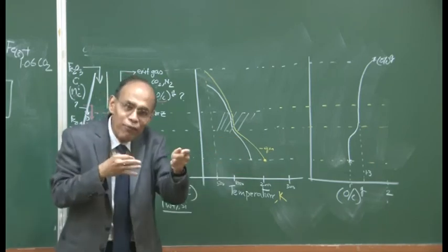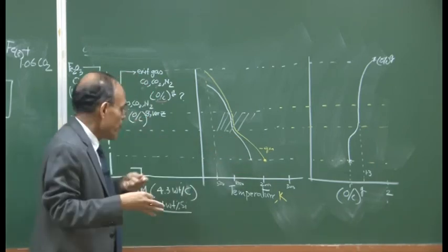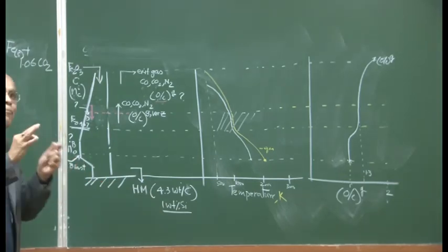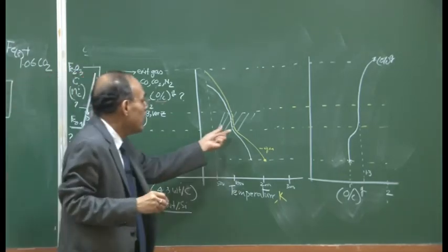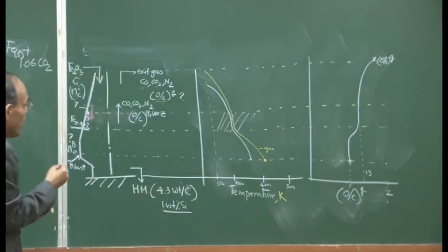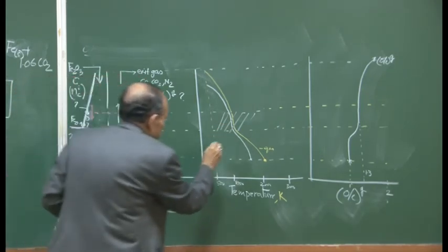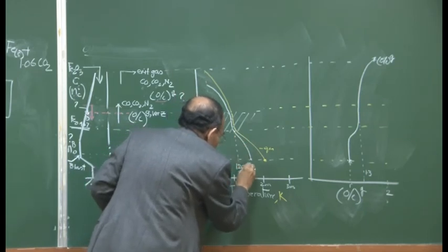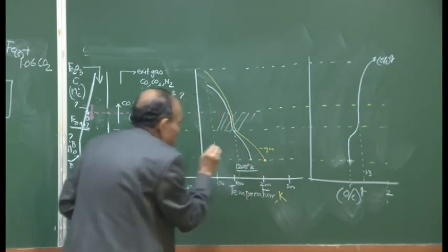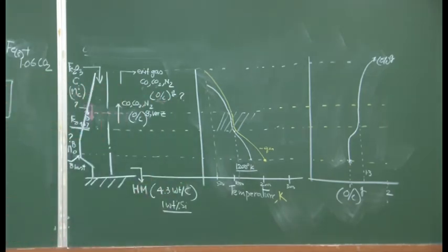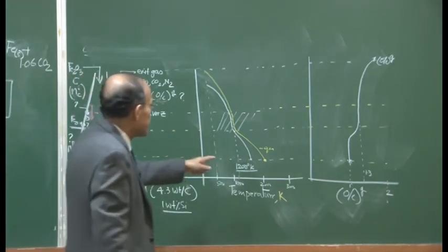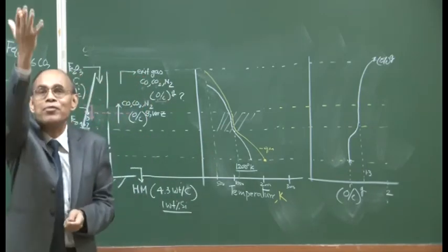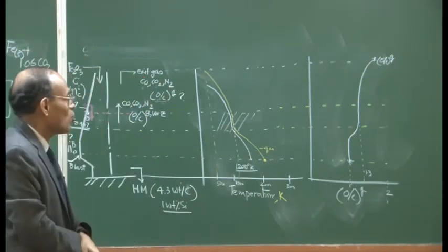In the process of ascending of the gas and the descending column of the material, at some point they will come to nearly identical temperature, and this temperature is 1200 degrees centigrade. At 1200 degrees centigrade, there seems to be thermal equilibrium between the ascending column of gas and the descending column of solid material.